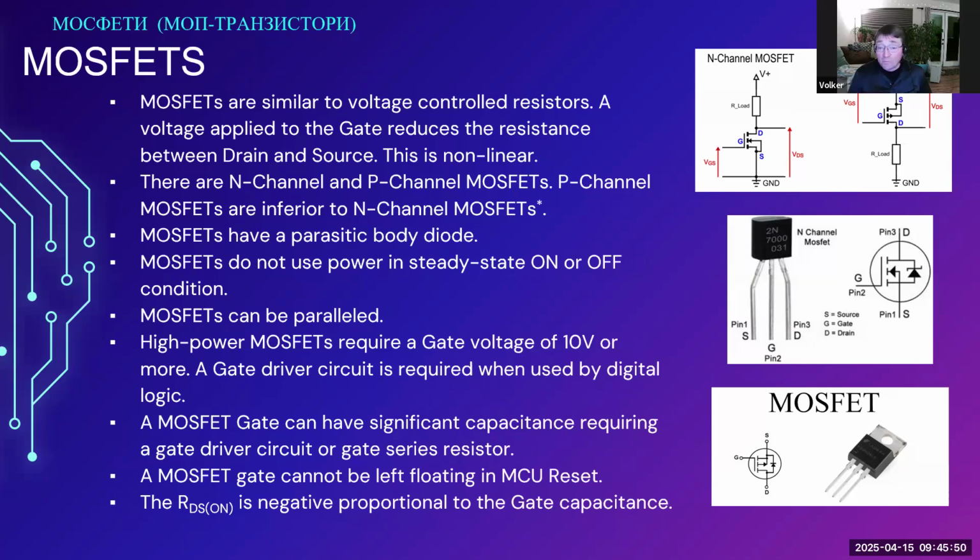So where you need one resistor for a transistor circuit, you need to implement two resistors for a MOSFET circuit. This is not a problem, resistors are dirt cheap. But when you're designing your circuit, never forget the pull-down resistor for a MOSFET.